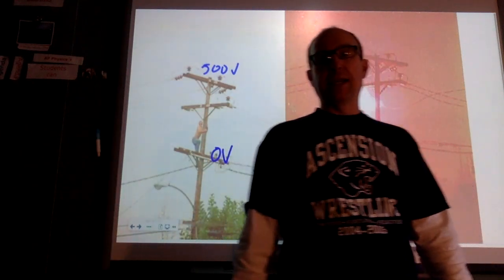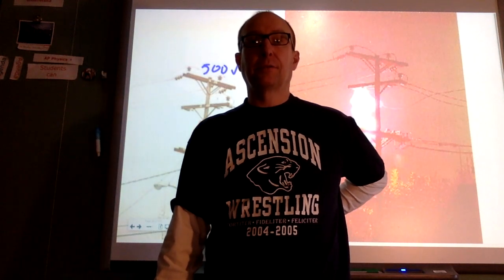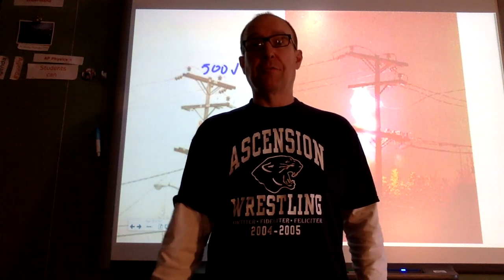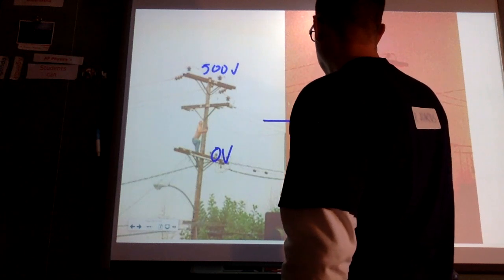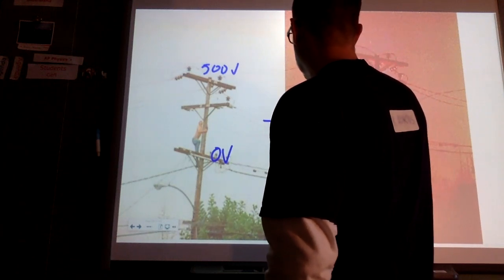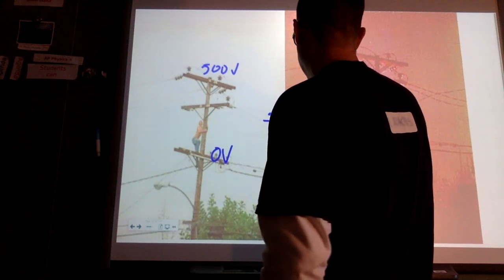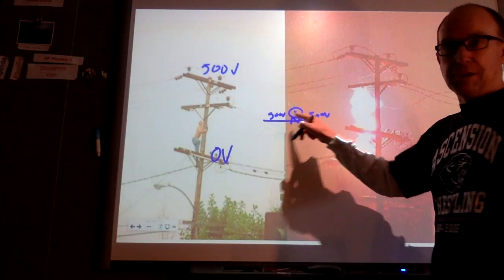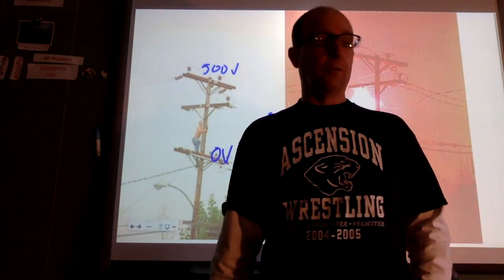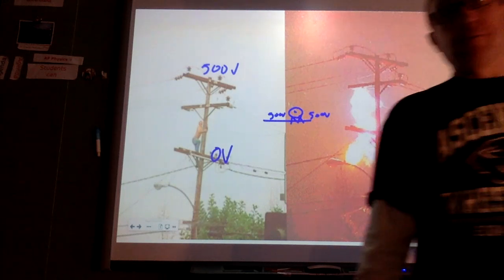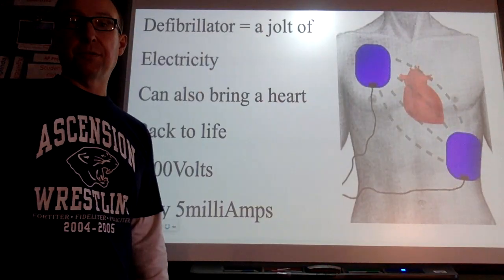And that's why birds can land on non-insulated wires. A lot of wires, the insulation just falls off of them and they're just bare wires. A bird can be just sitting up here on it, and because it's 500 volts here and 500 volts there, there's no difference in potential across its feet. There's no reason why current would flow through the bird. And they do that because they're warm. So if current's flowing through them, then there's some heat that's associated with that.